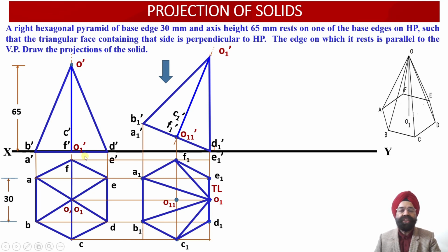So we know the dimensions of the longer edge as well as the shorter edge of this rectangle. Now using the principle of transferring the rectilinear distances, we are going to rotate this plan projection view which we had earlier obtained corresponding to this inclined hexagonal pyramid. So let us have the rotation or translation of this plan projection view such that the edge D1E1 becomes parallel to the horizontal plane. That is, we have to rotate this plan projection view by 90 degrees.